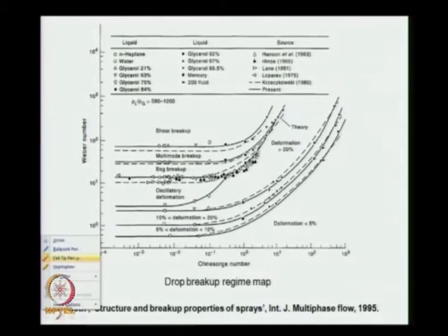So, we will start from this corner because it is the easiest to understand, I believe. If I have an order 1 Weber number, this is our raindrop that we discussed earlier, Weber number wise. But instead of raining water, if it was raining glycerin, which is let us say 1000 times more viscous, then this is essentially where our glycerin rain would fall.